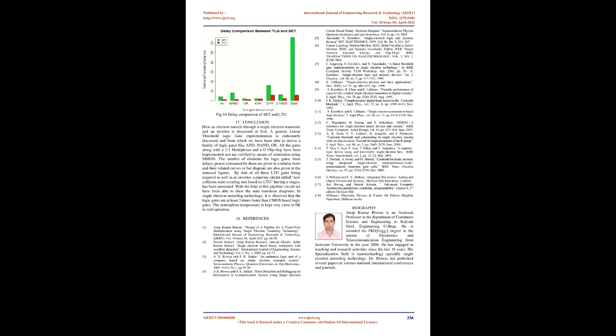The time delay/processing delay for a CMOS logic gate like NAND, NOR, XOR is 1/2 ns, whereas the time required for tunneling through a single-electron transistor, SET, is approximately 4 ns. The XOR gate using conventional logic circuits requires 16 transistors, whereas the same function can be implemented with the help of just one SET, i.e. the number of nodes can be reduced to 1 in lieu of 16.